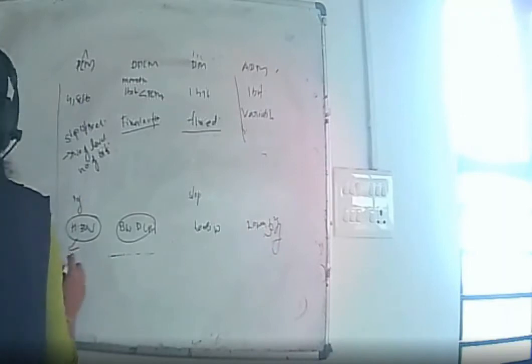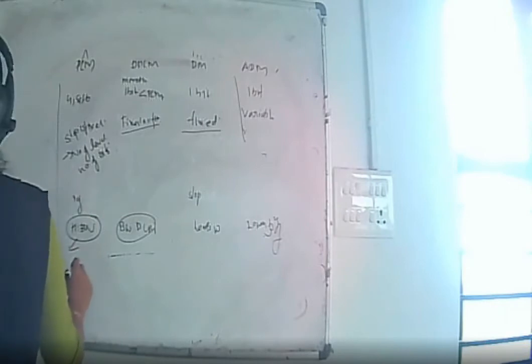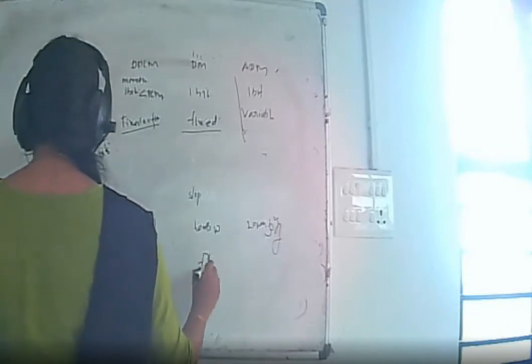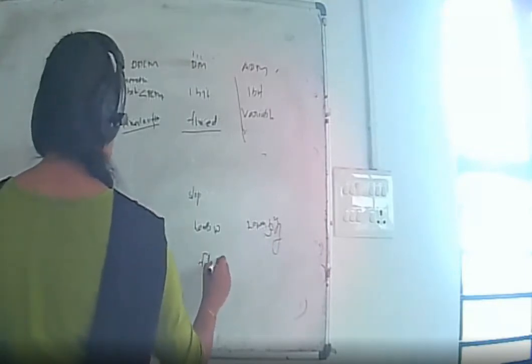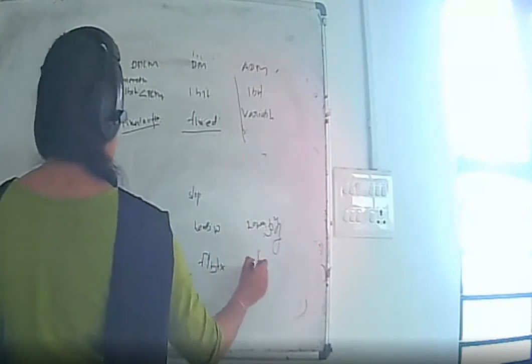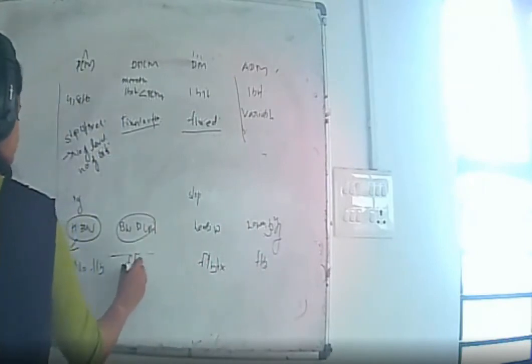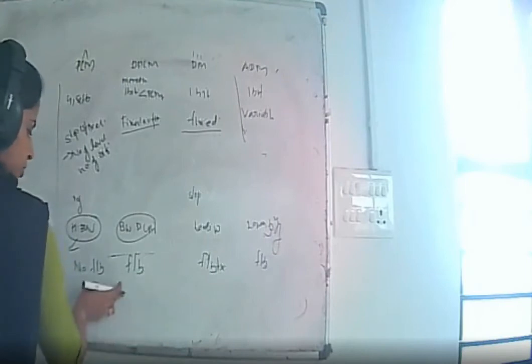Telling about the feedback, there is no feedback in transmitter and receiver in PCM. In delta modulation there is feedback in the transmitter side, and in ADM also feedback is present, and DPCM also feedback is present in the sense that we are taking the output from the prediction filter.